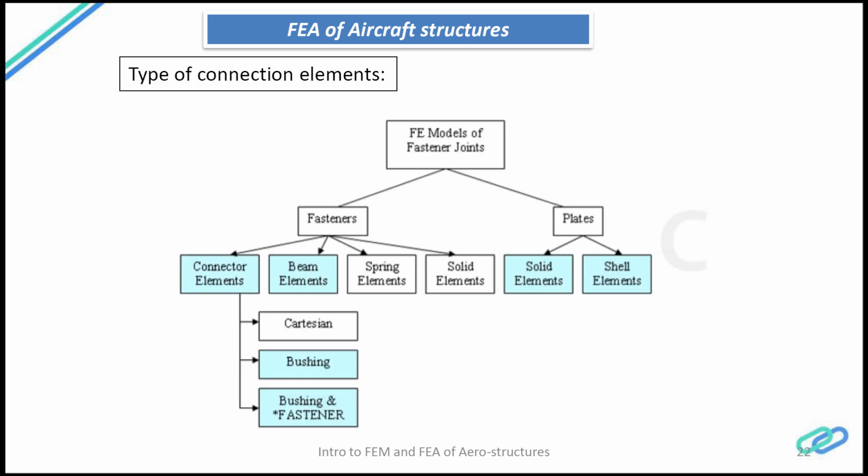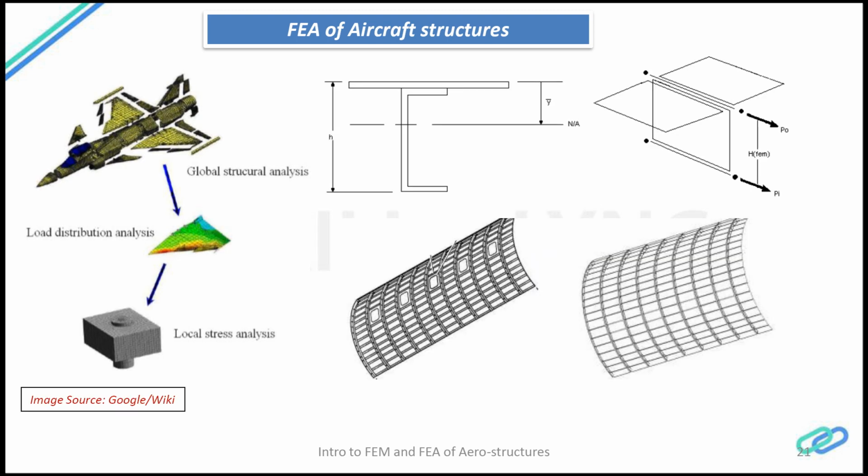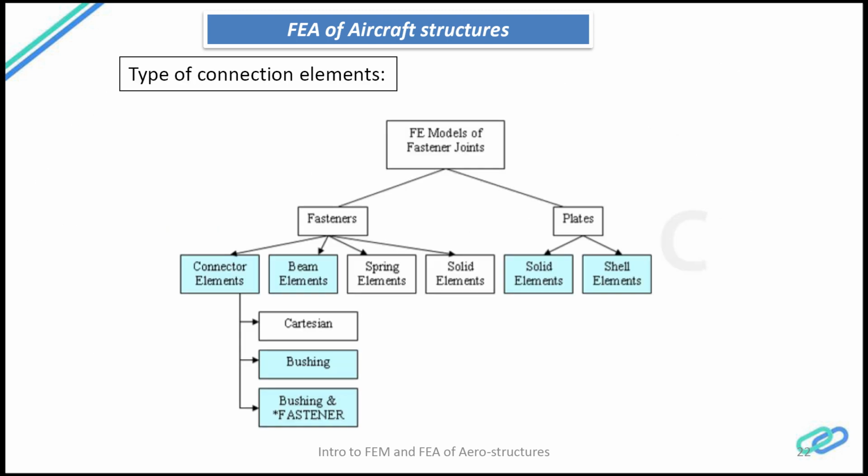Now moving on to the types of connection elements. I have put this topic separately because it is a really important topic, and each and every user needs to understand the importance of these connection points, because your connection points are where you apply the boundary conditions or sometimes loads.